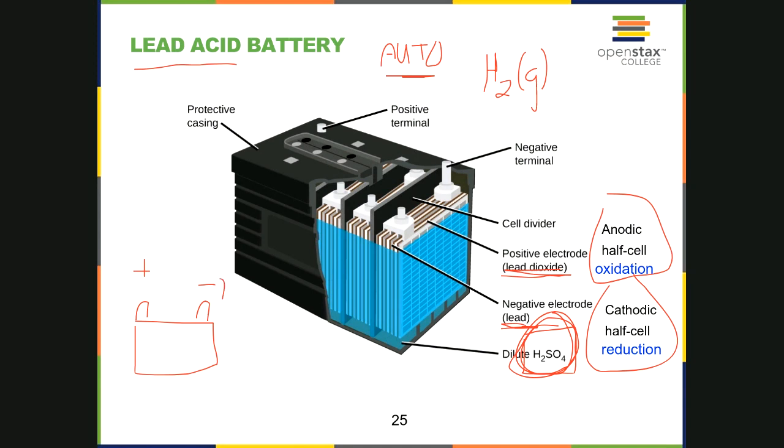But you would first connect your wire between the positive connectors on both of the batteries, the one that's charging and the one that you're charging from. Then in your car, the negative terminal should be going to what they call ground. I'll do the symbol for ground. It's like a little triangle made out of lines, but it should be attached to a metal part in your automobile.